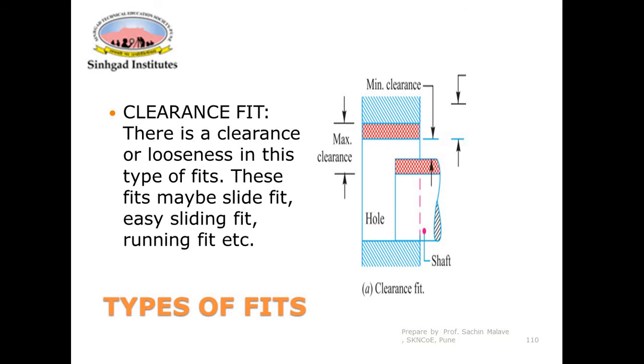So in any extreme case, this difference is positive, which means the minimum size of the hole, this one from here to here, is larger than the maximum size of the shaft.